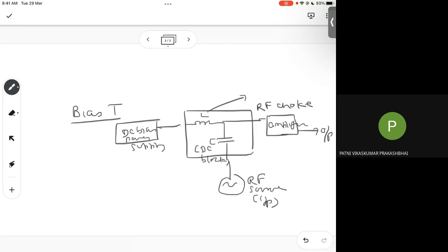A typical RF source, which we have in our RF lab, which you will be using as an elective in third or fourth year, as I told you. You will find that one RF source instrument costs around 30 or 40 low signal function generators, which you use in basic electronics. So this is something used as a precaution. We always use bias T, because DC is a low frequency, and this is at high frequency. So one frequency should not damage the other one.